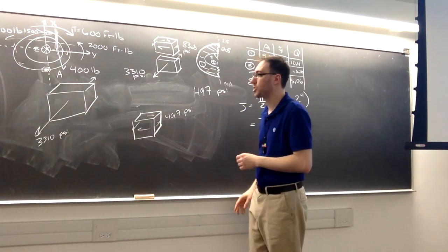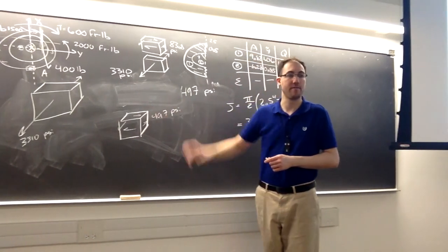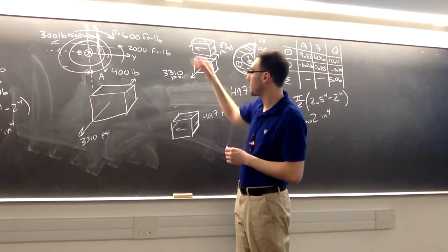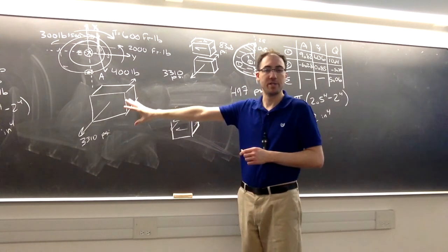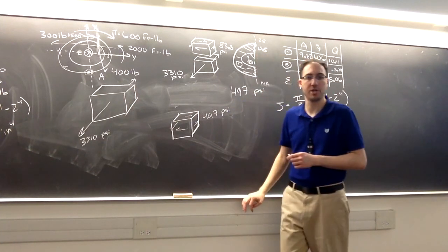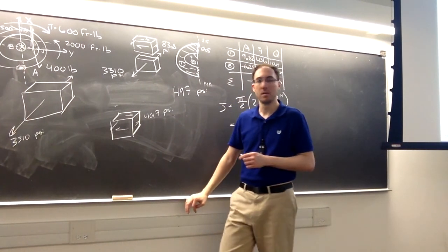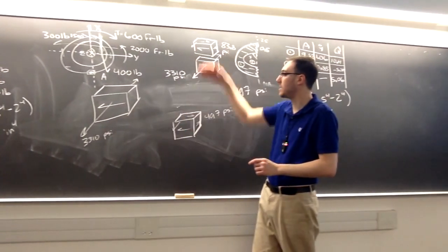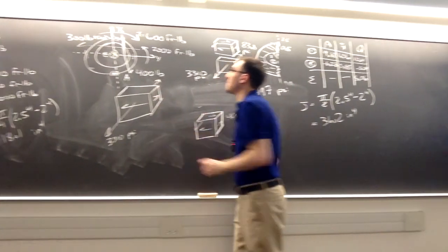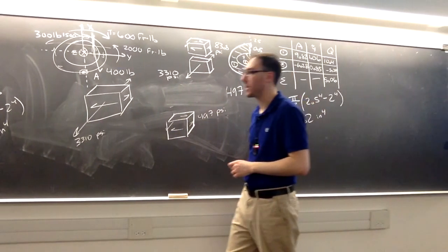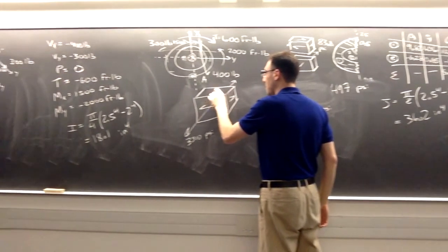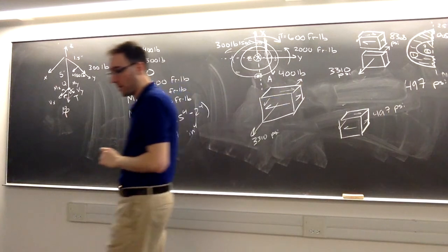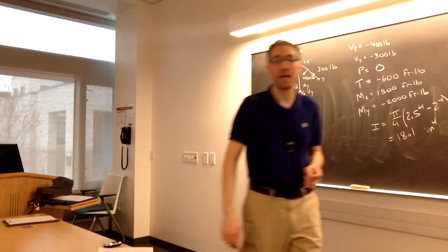So what will the total shear stress be in aggregate for this object? Again, this pulls the front face to the left, this one also to the left. So in total, what happens according to the shear stress? Right, they're going to add together because they both go in that same direction, so it's an additive effect. And right, we just have to add the 83.8 to the 497, and then it's going to be, I'm trying to draw on the back face here. The shear stress state then in total is going to be 581 psi.